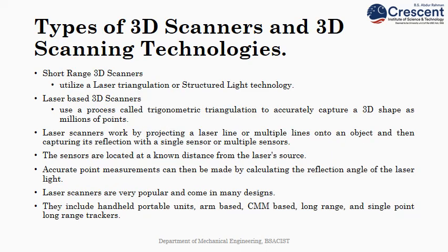In reverse engineering, primarily it was mechanically disassembling, measuring the parts, and redrawing them. That was the traditional method. But with the advance of very powerful 3D scanners, it is very easy to capture an object's contour with millions of points and then recreate a 3D model. From the 3D model, the 2D model can be made.